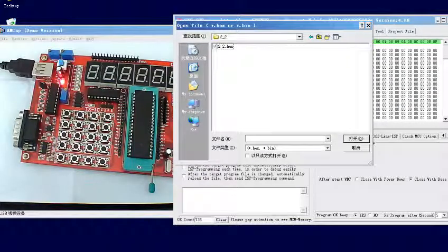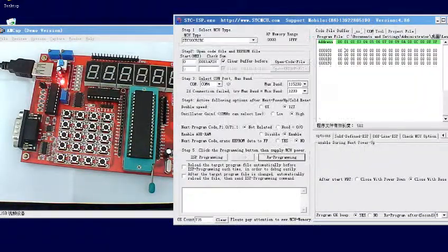This is the file that can be recognized by the microcontroller. It's all 010101 based. We can't read it, but the microcontroller can. So always remember the one you select is a hex file. Highlight the hex file and press OK. Now we have selected that file. Next step is just to press this button here, Programming.